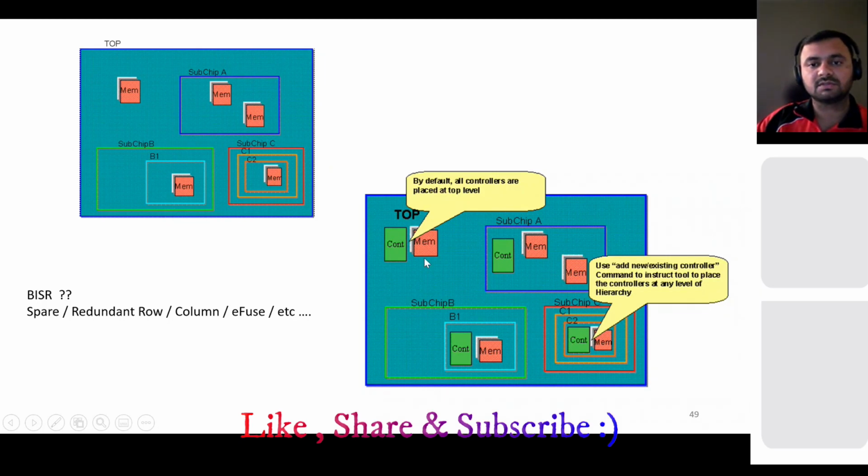To store those responses or that information, we use eFuses. At the top level, you have an eFuse where you store all that information, like the redundant row and column information and their addresses, and you generate that repair logic from there if there are any faults. This is how memory BIST happens. BISR is not required in every chip, but self-repair is there. Many in the industry use these self-repair techniques.